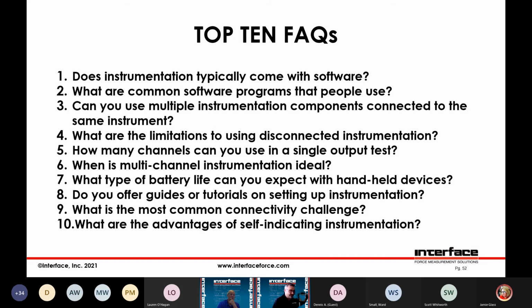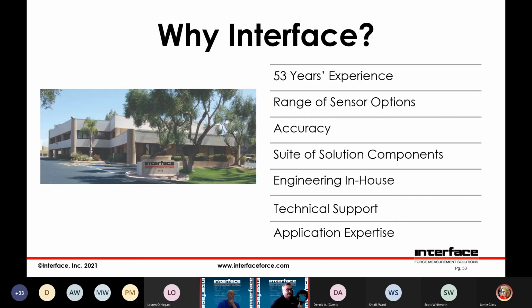And if it's reading correctly, well, you know it's some problem with your PLC or the cabling between the instrument and your PLC. On the other hand, if the display isn't reading correctly, you don't need to mess with your PLC, right? Because you know that the problem lies in the actual instrument or the load cell or cabling between the two. Next slide.